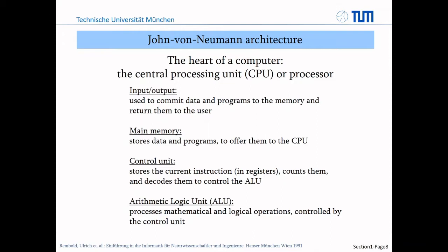The decoding can be quite simple, like we did here in our arithmetic logic unit. So we just set the bit sequence in our control word and then the arithmetic logic unit directly knew what should be done. But it can be much more complex. It can be a microprogram so that a special control word starts a sequence of new control words. And therefore, this control unit can be really complex.